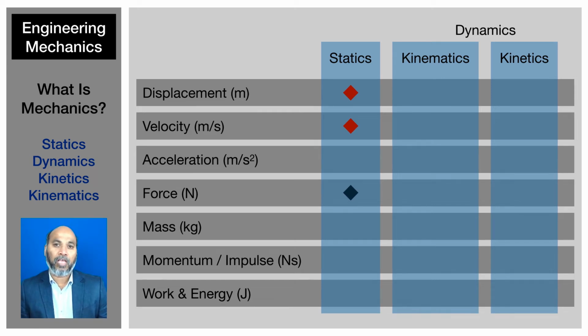So there is an absolute displacement and velocity there, but there is no relative displacement and no relative velocity. In order for you to say this is statics, there must be no relative displacement and no relative velocity, in which case you can just analyze the forces, and that is what statics is all about.